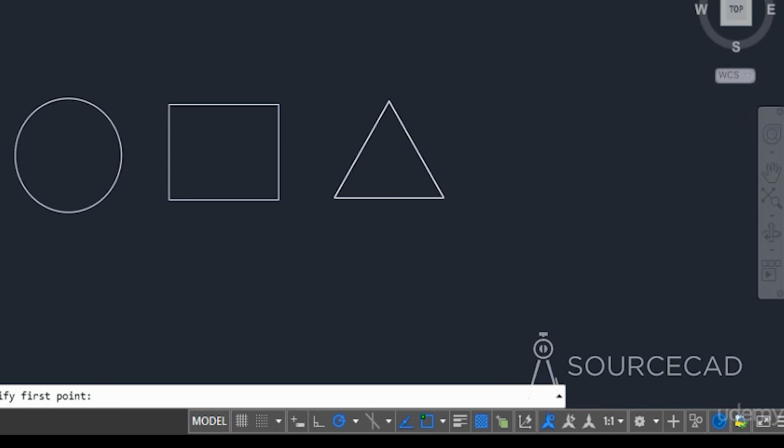So simply go to that command and left click, and the command will now be activated. And once the command is active, you'll notice that its name and also the instruction will be visible on the command line, and also the cursor will change into this point selection cursor or into a pick box. In order to exit this, simply press the escape key. You can press escape multiple times also if you want, so that will not make any change to the drawing.